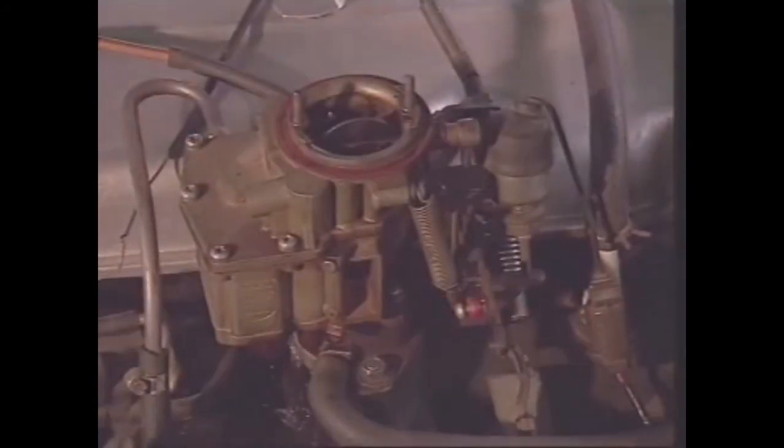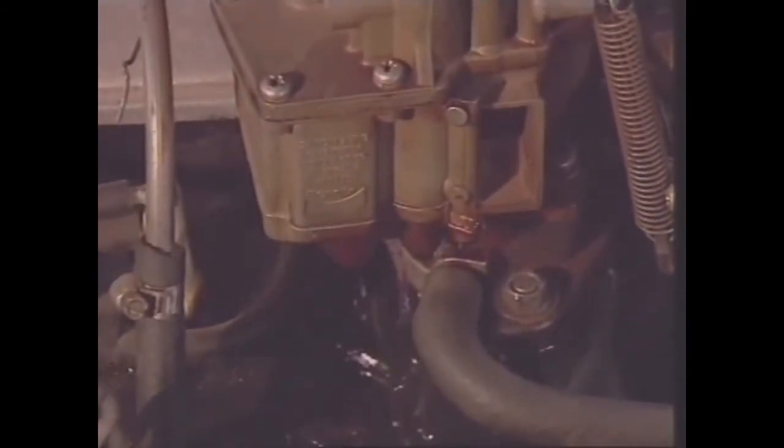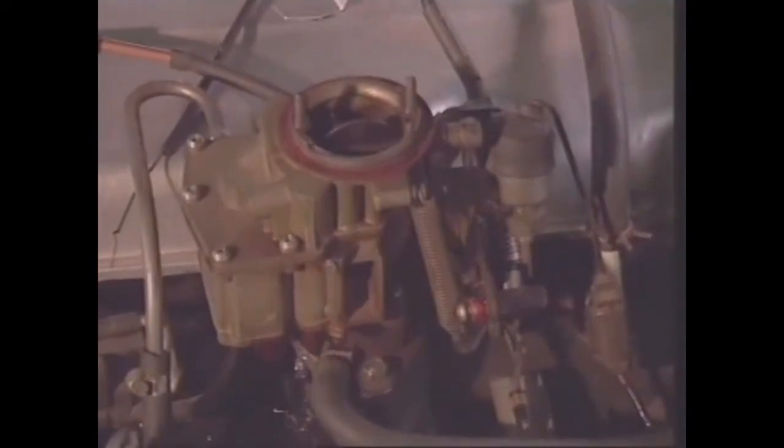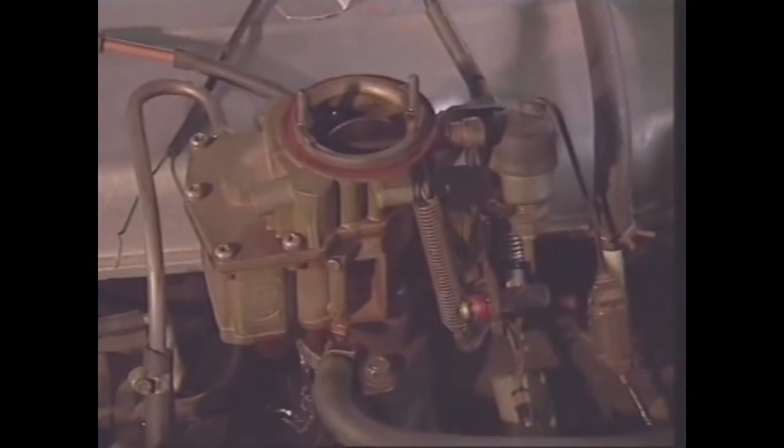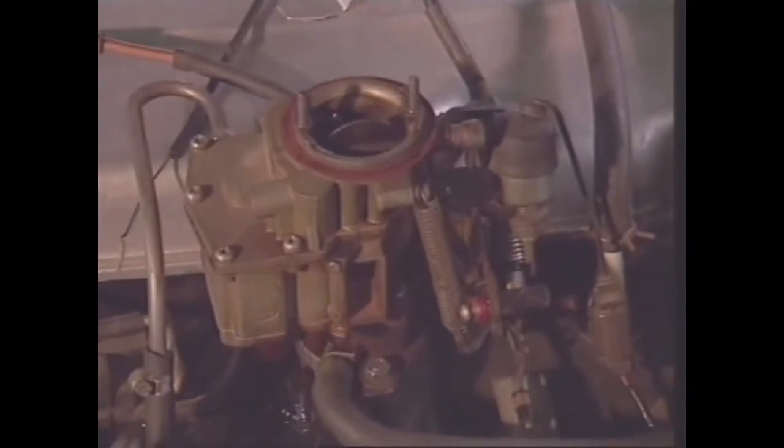The choke should operate as briefly as possible. Overusing it produces rich mixtures that cause exhaust pollution and increase fuel consumption. Flooding a carburetor also produces rich mixtures. This can be caused by wear or by dirt trapped in the needle and seat that causes the level in the float bowl to rise and fuel to discharge from the nozzle, with little or no venturi action.